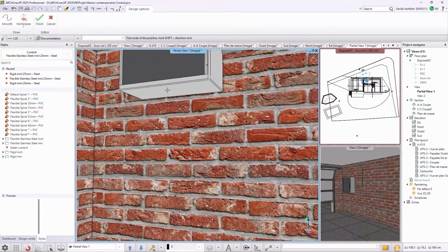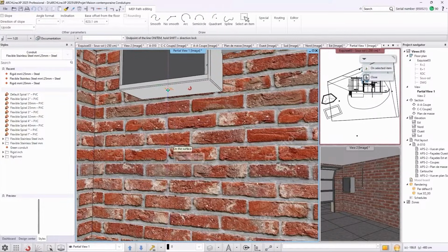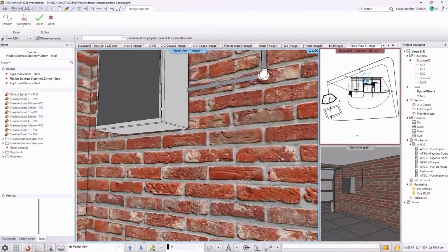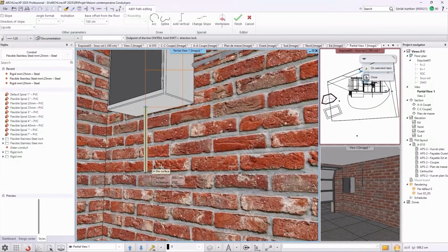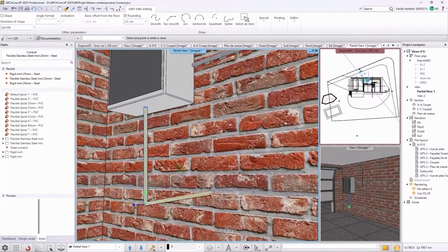Select the starting point of the conduit and set the reference plane. If you don't find the right starting point, adjust the viewing angle in the 3D view. Add the length of the conduit and create an L turn into the path. You can set a new plane at any point of the drawing process.